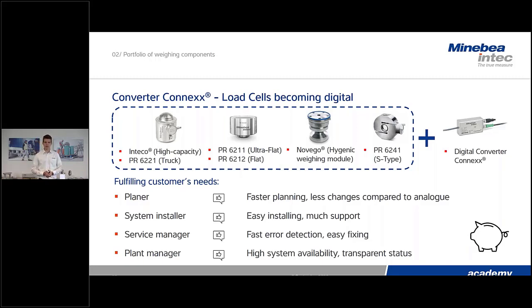It leads, for example, to faster propagation times and individual communication with the load cells, which is really helpful for the service technician, for example. Among others, you don't need a cable junction box anymore, which makes the commissioning faster and easier. With this product, we focused on the customer needs to make the work at every step easier and offer more reliable weighing options.